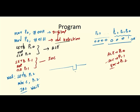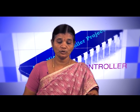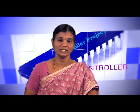Now, after that, the digital data is available on P naught. If you want to store it in any one of the registers, you can do it by giving the instruction move R3 comma P naught, or if you want to store it in a specified location, you can give move 40 comma P naught. Okay. This is for memory storage, and this is for a register. So, this is the way we develop the code to read the data from a particular channel.